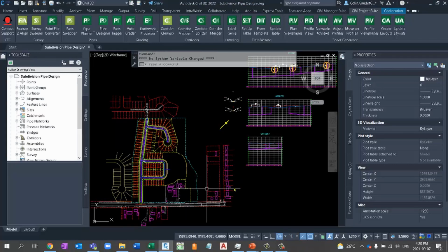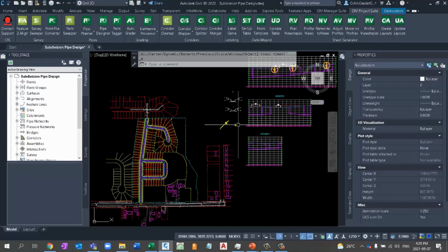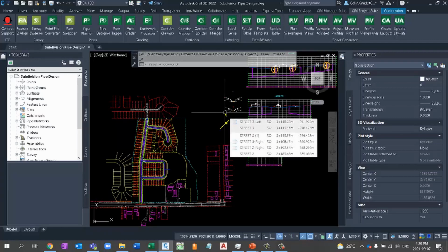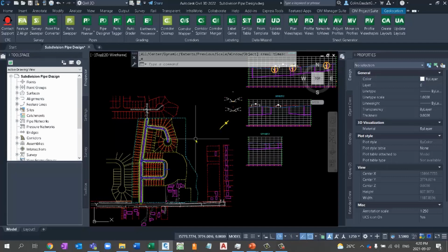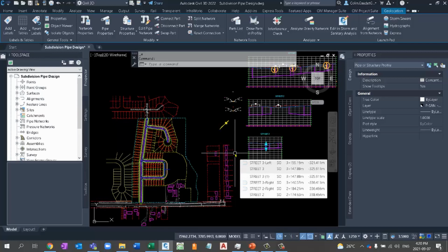Once we've completed the network design and the pipe layout, both in the horizontal layout and the vertical layout, we need to then convey that information to everyone else. For other designers, we can do that in the form of labels. But for anyone who's not using the design software, if we don't want to have to create a full, nice looking PDF to translate that information, a lot of the time we're doing that via Excel tables or different types of reports.